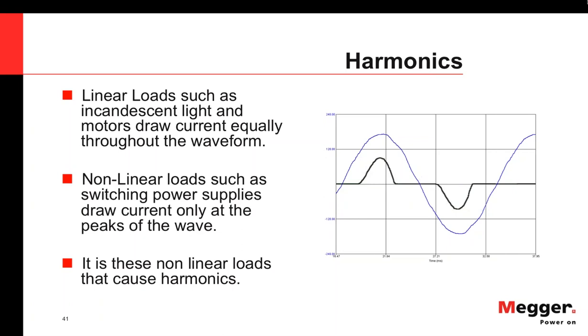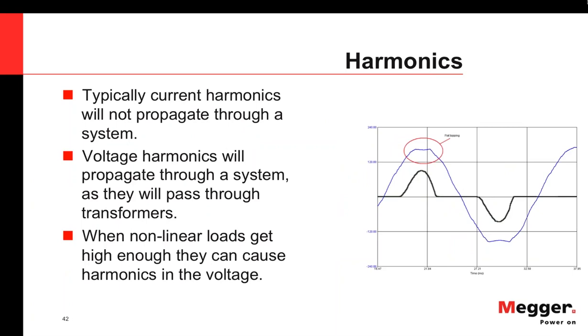Now, linear loads such as incandescent lights and motors, when they operate, draw currents equally throughout the waveform, so they do not create harmonics. However, today we see many more nonlinear loads, and they are ever increasing. Nonlinear loads, such as switching power supplies, draw currents only at the peak of the wave, so they do not draw current equally throughout the waveform. It is the nonlinear loads that cause these harmonics.